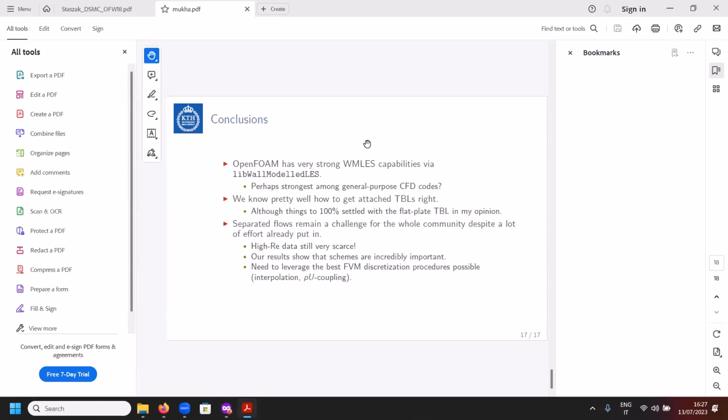Yeah, just linear interpolation between the cell centers. Say again? Yeah, so when I was running those, I wasn't aware of that, but that was a good option. It's a trade-off because you preserve energy, but you also lose second-order accuracy, right?